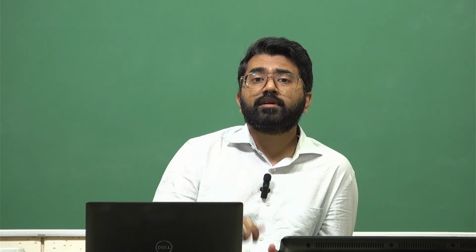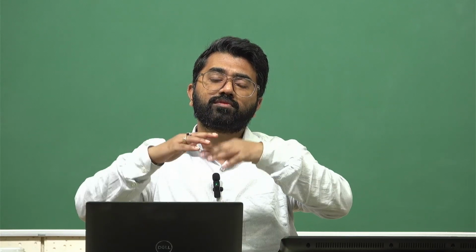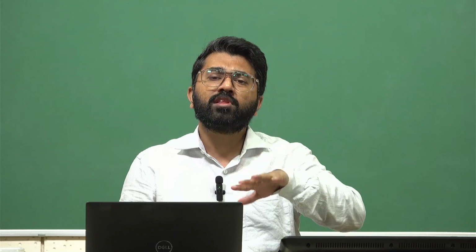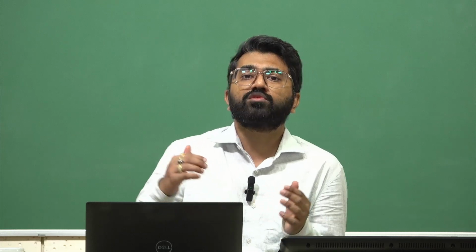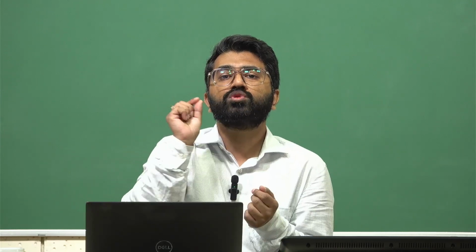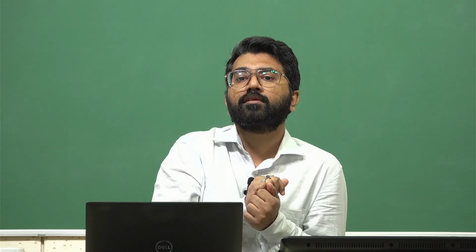Yes, you can in certain aspects where you have scanned models. Scanned models are already in volume form, and you can use them directly. But here I would like to mention one caveat. Do not think that quickly doing an MRI scan or some form of hand scanning is going to save you a lot of time, because those models are extremely crude. They have a lot of jagged surfaces sitting one on top of each other with a lot of gaps, so they need a lot of post-processing. You need to send them through software to make sure it is a closed volume, with no small micro gaps and things like that.